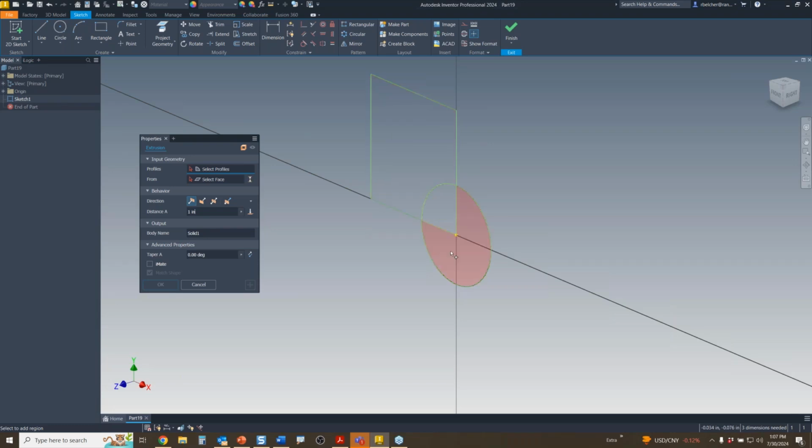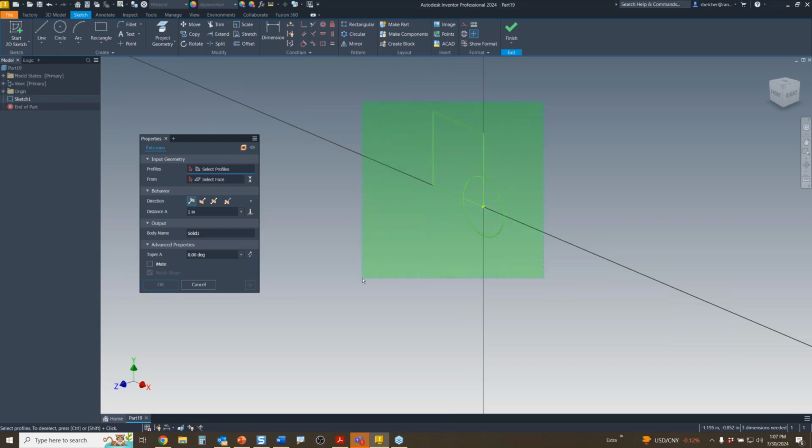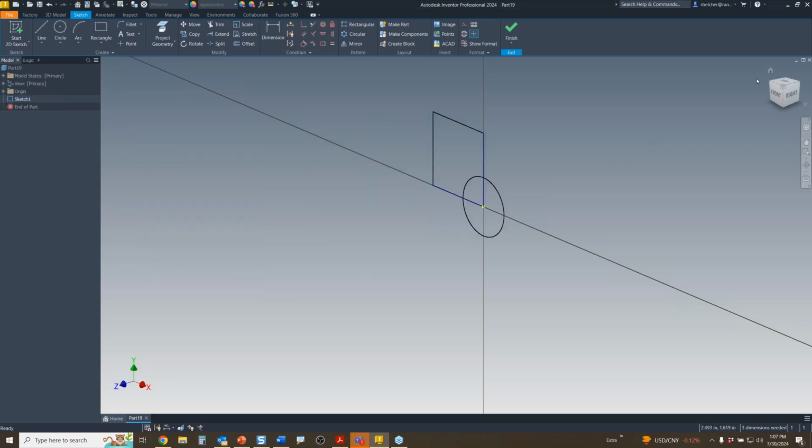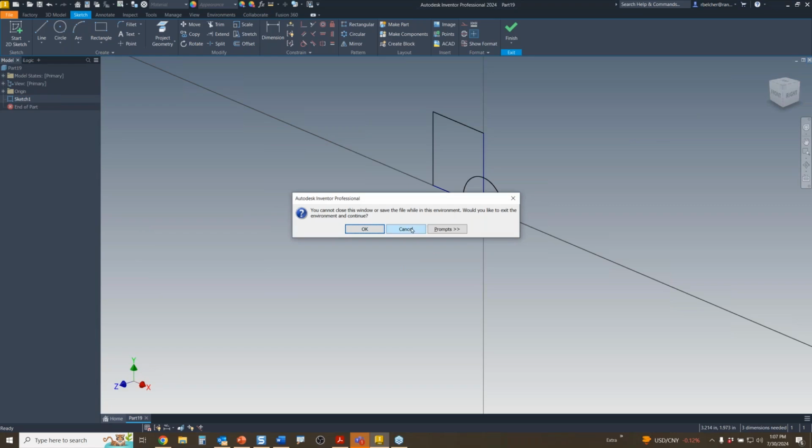It's just a boundary. Or you can select the object: if I click on the lines of the object, I can get those. You also have window selection. You can just window select all of it if you want to. Those three selection methods are at the core of some of the first demonstrations that I want to do.